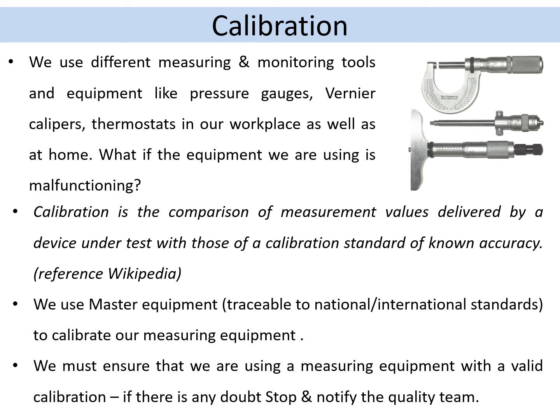We have to ensure that we are using measuring equipment with a valid calibration at all times. If there is any doubt, if there is a sticker missing, if there's a wrong date on it, or the date is expired, stop and notify the quality team, please.